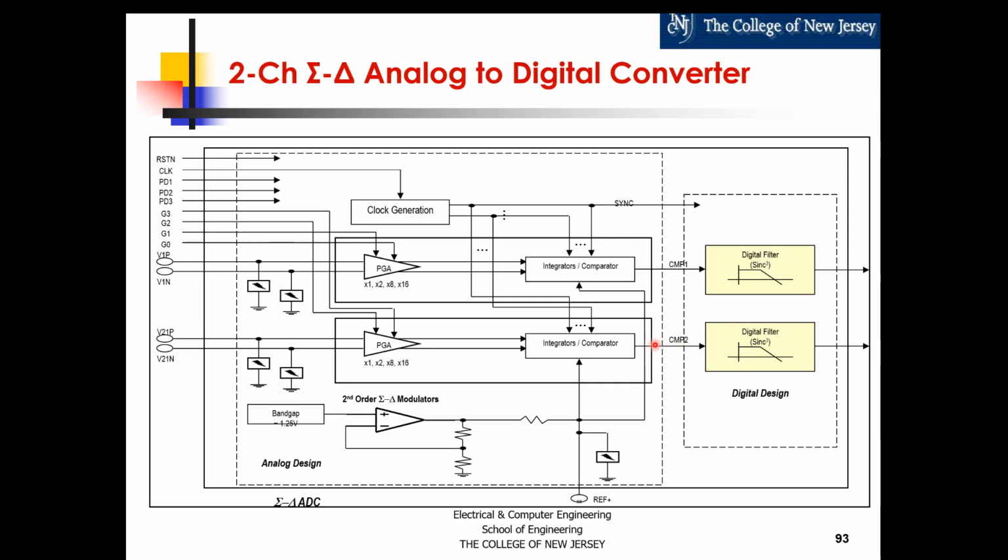So here we have a high speed 1-bit digital input, and here we're going to get, after this digital filter, which is going to decimate the high speed 1-bit digital stream, when it gets decimated by this low pass filter, we get the number of bits that we want from the overall analog to digital conversion, noise free, but at a lower speed that is in the bandwidth of interest of this as a product, the analog to digital converter.